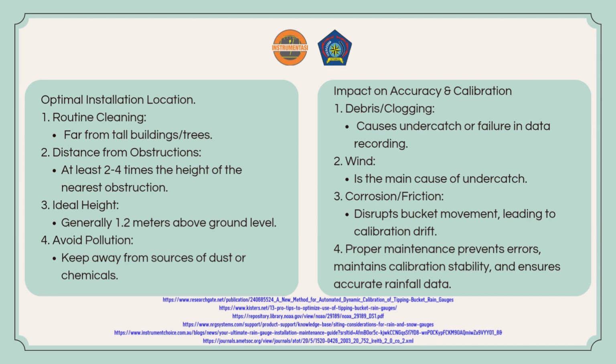Fourth, connecting the sensor and power. Connect the sensor to the data logger. Also connect the solar panel and battery if using one. Make sure all cables are safe from water and weatherproof.